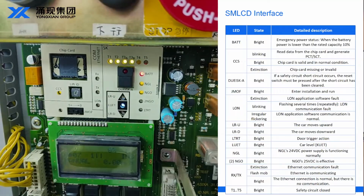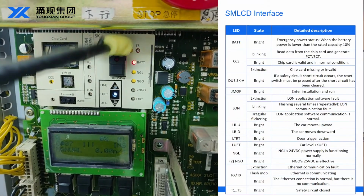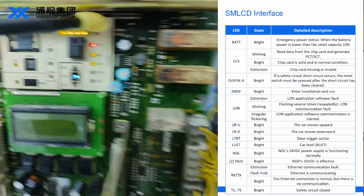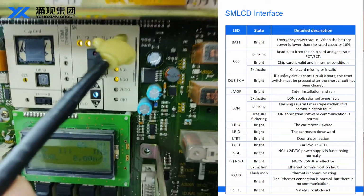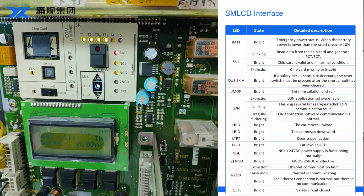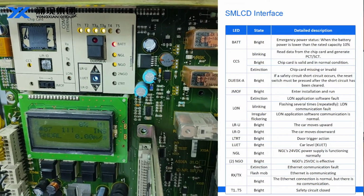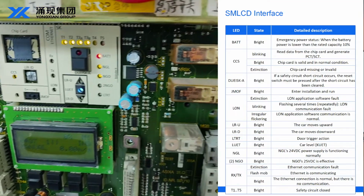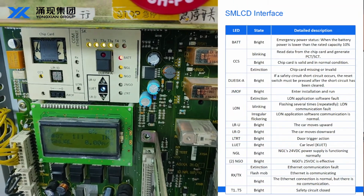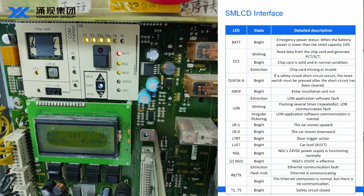Next is this part, T1 to T2, T3, which I explained earlier. This is our safety circuit, and also the car door lock, which is a very important light. T1 to T5, this light is for the safety circuit, but as you can see now, our T4 and T5 are off. T4 and T5 represent the car door lock, so it means the car door lock has some problem.